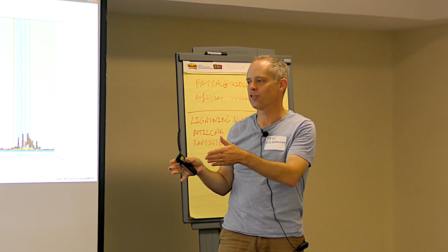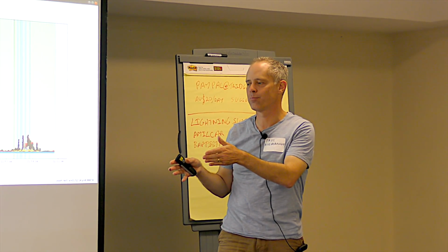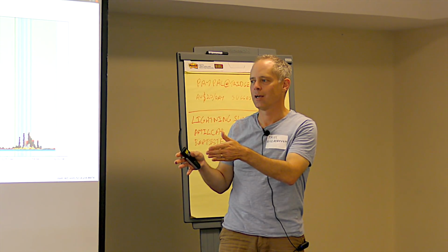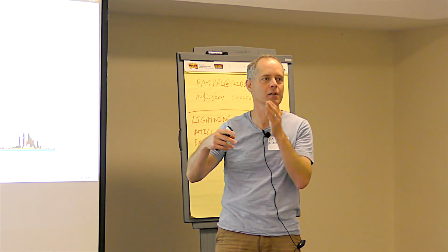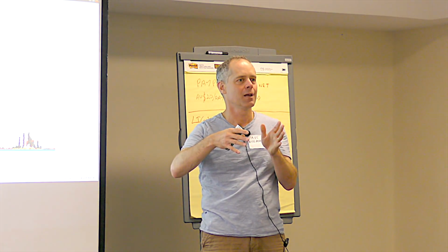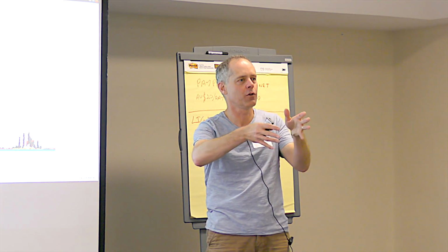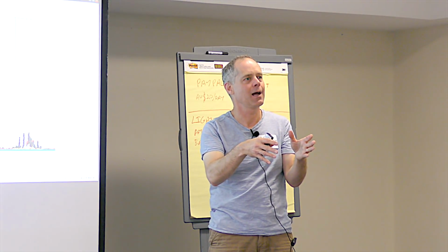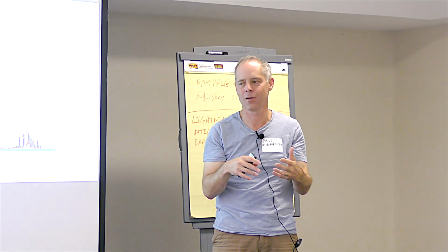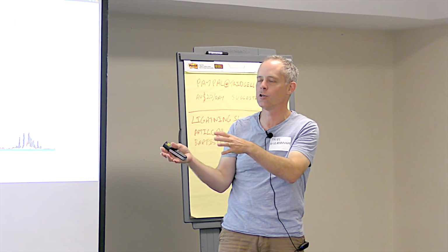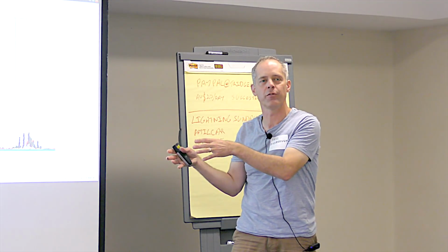However, the inertial nav system thinks, well, I'm pointing east. It sees that movement and it interprets it as a movement to the south. In other words, the inertial navigation system will take its dead reckoning of the accelerations, and they're going to be rotated by 90 degrees. So the inertial navigation system will think that the vehicle's moved south.